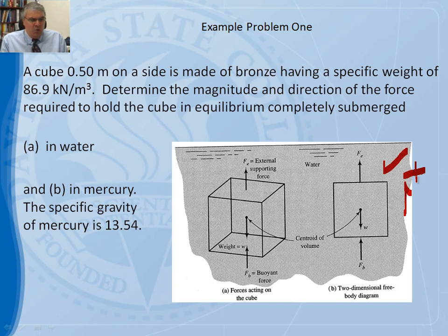force, any unknown after we calculate them, turn out to have a negative sign, that means the original assumption that we made for the direction of the force is incorrect, and we would go ahead and change that on the free body diagram. One must be very careful to stay consistent throughout the calculation with the sign convention that we agreed upon.